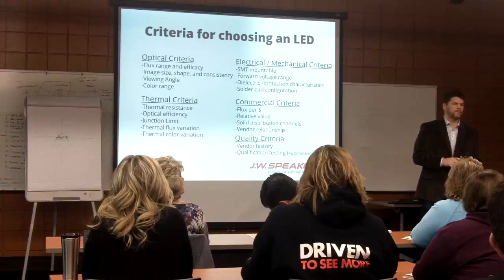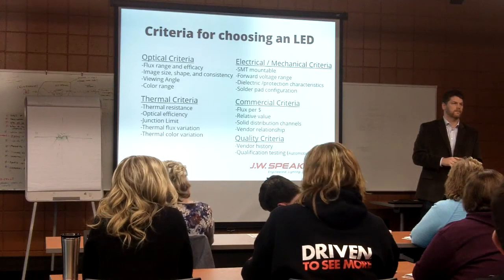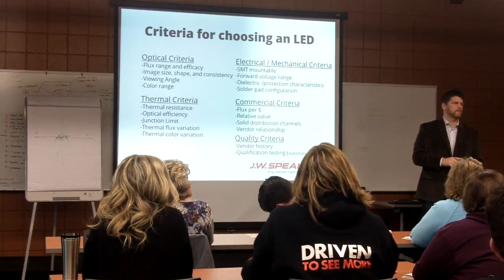In other cases, if there isn't a direct replacement that is fit, form, function the same, it's a huge deal, because then we basically have to redesign the circuit board for the LED. We have to make sure that optically we're okay. And then we do have to re-homologate everything, recertify everything. Every certification that lamp went through, we basically have to repeat. It's very dependent on the customer, market, and what you do with it. Even so, we try to get away with as much as we can.